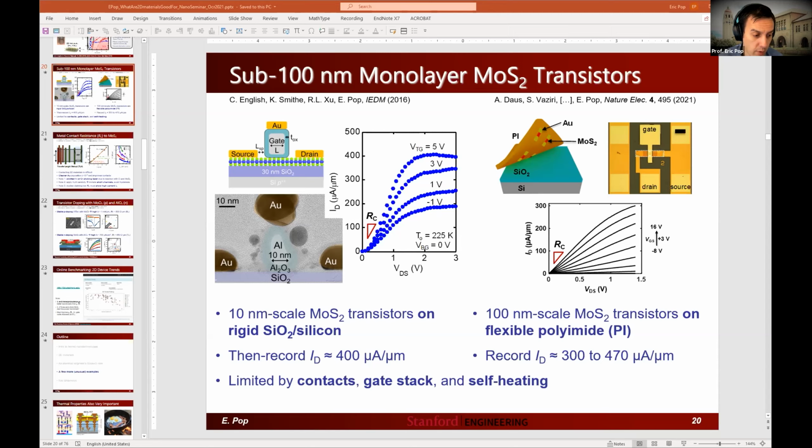Right, well, that's a very difficult question. We are using 2D dielectrics. I didn't show any of it here, but right now, if you look on the left, the dielectric that we're using here is just pure old aluminum oxide. And the aluminum oxide is clearly not good enough. It's not high K enough, and it's also still kind of thick. It's too physically thick, and it's not high K enough, and that's why we were not able to shut down this transistor properly in these experiments.